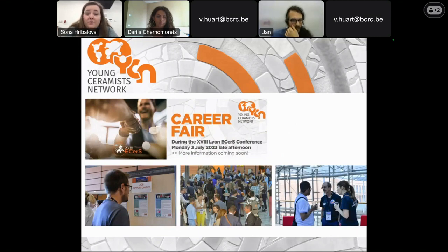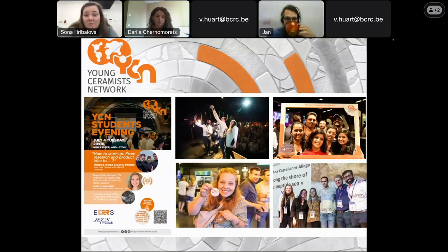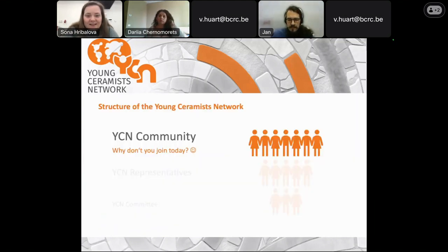Okay, so as I said, the microstructure is what defines scattering or the transparency. And this is something that we can actually calculate or at least estimate. If we take a very simple example, let's say one slab of 1 millimeter thick yttrium aluminum garnet, which is one of the typical transparent ceramics, at a laser interesting wavelength of 1030 nanometers, and you have this much porosity.